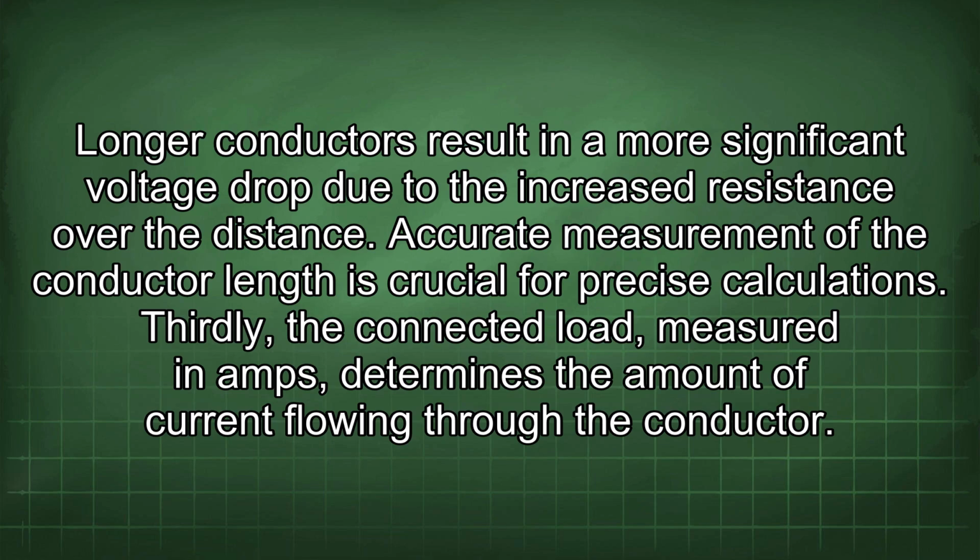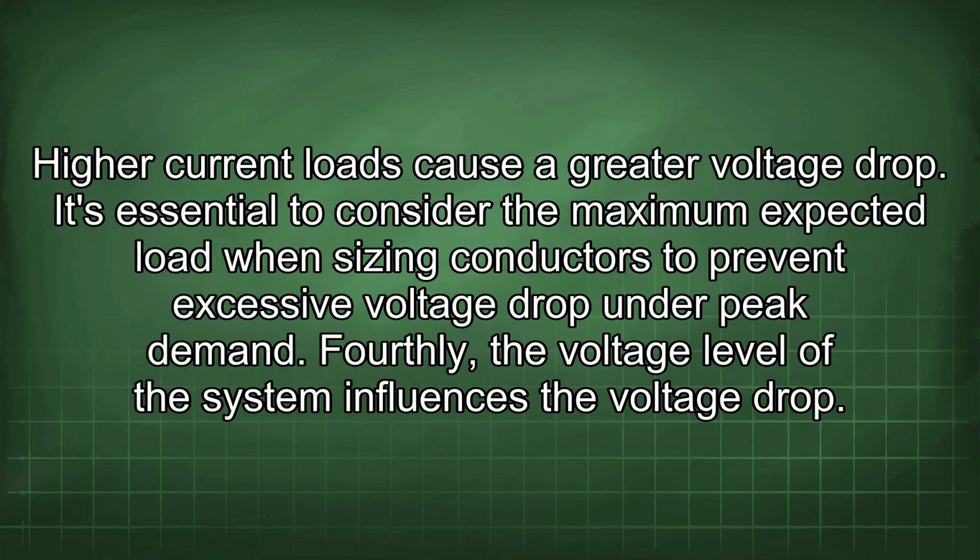Thirdly, the connected load, measured in amps, determines the amount of current flowing through the conductor. High current loads cause a greater voltage drop. It's essential to consider the maximum expected load when sizing conductors to prevent excessive voltage drop under peak demand.